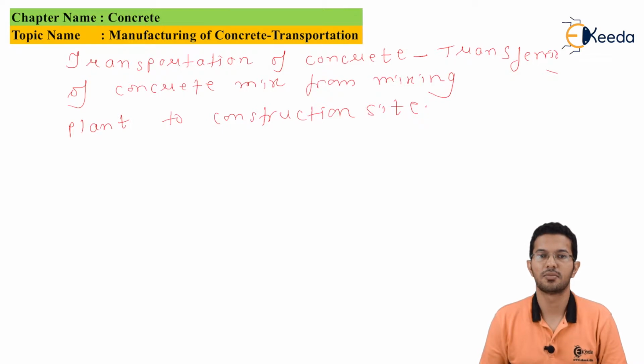This handling may produce segregation and loss of slump if the distance is long. The successful placement of concrete is dependent upon careful mixing, the proper equipment, and adequate transportation. This site will define, analyze, and demonstrate the importance of each in the overall process of placing concrete.